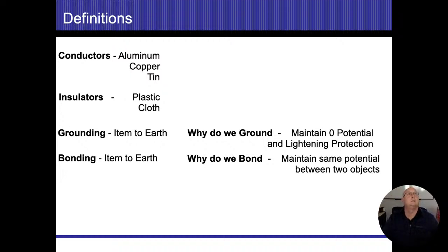I'd like to address a little bit about these. So aluminum and tin, a lot of people get confused between the two of them. Now, they're both going to be silverish in color when it comes to looking at the actual metal portion of it. Aluminum will be a little bit shinier and newer, and I know I have a picture of it here when we get later on into the slides. But the biggest detail and the easiest way to tell the difference is that aluminum is always going to have the plastic insulation.